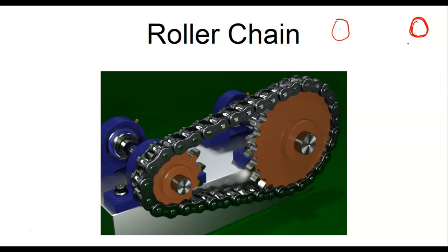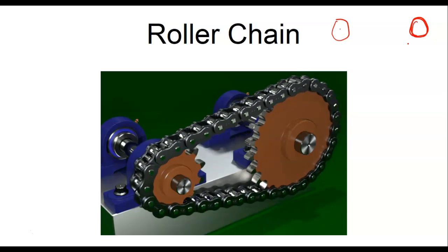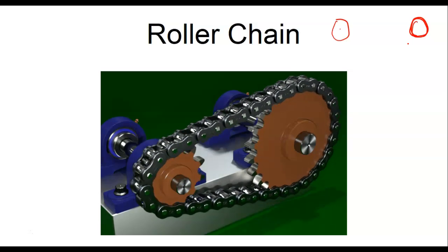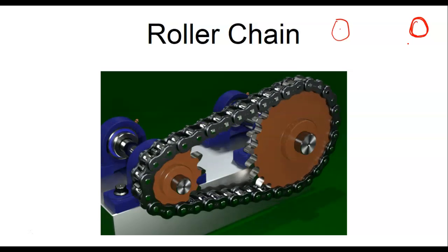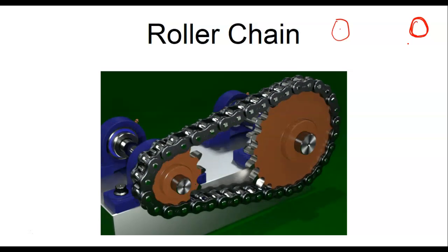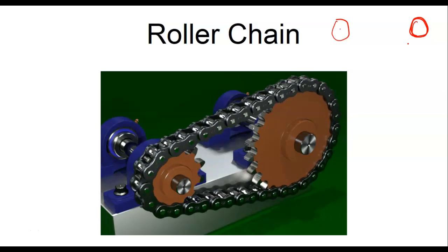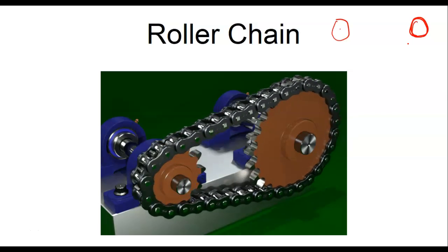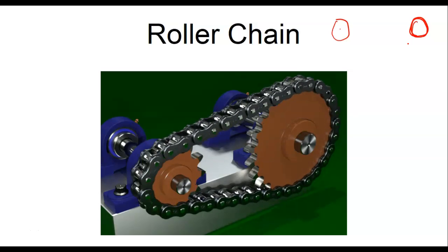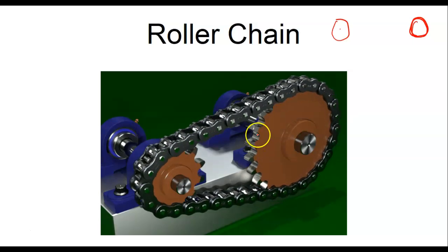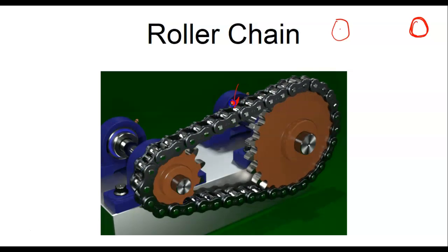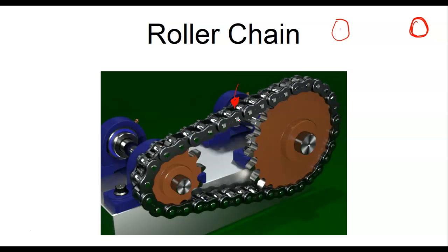Of course, the biggest problem we have on a motorcycle, one of my motorcycles was a chain drive, one of the first ones I got, is keeping your back wheel perfectly aligned. Because if it was off a hair, not only would it wear your back tire out faster, but it would also wear the teeth out on your gear assemblies. Anybody who's ever had a bicycle, sometimes if they're not perfectly aligned, the teeth of the sprockets would wear down. And plus, you've got to keep these things lubricated. That's the biggest problem with a lot of people and bicycles. They don't lubricate their chain.